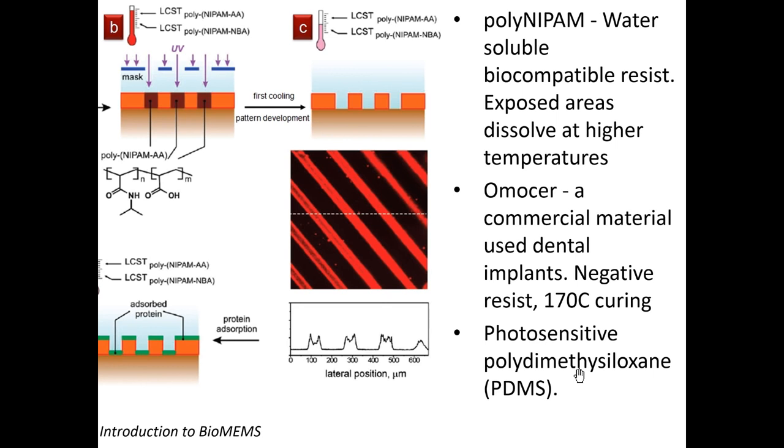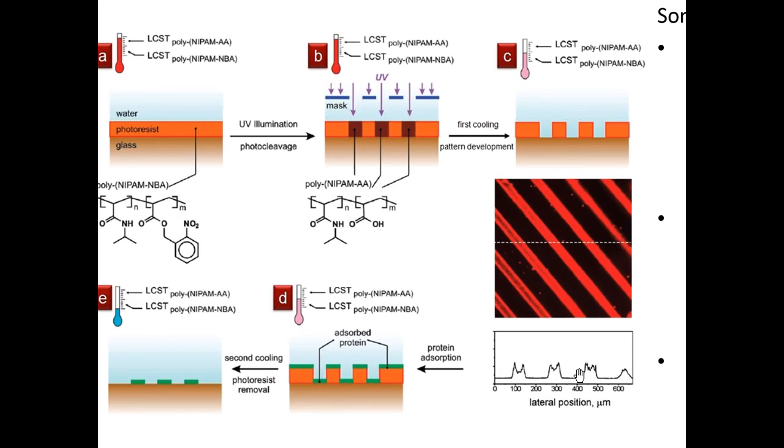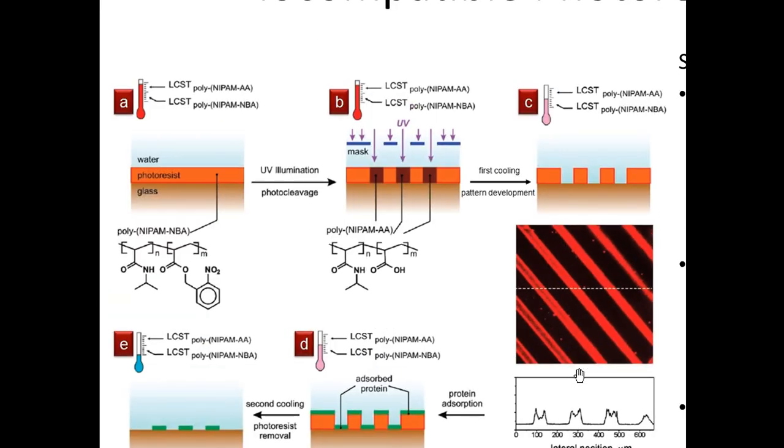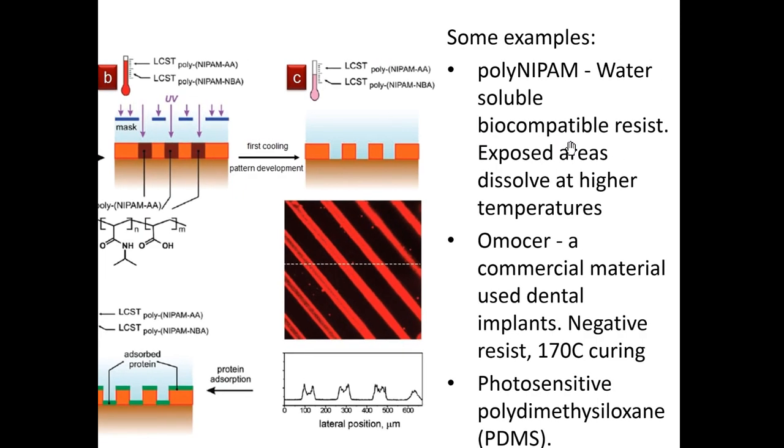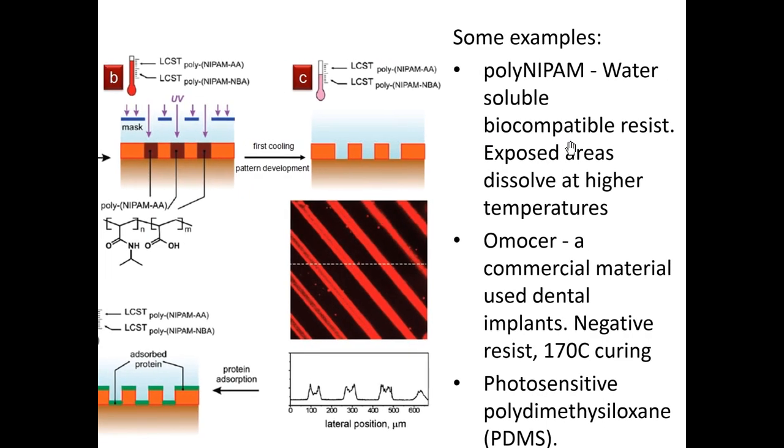So you're not heating this material up. It's just at room temperature, and then you're cooling it. It doesn't show a heating step at all. Oh, so what's happening is that you're exposing the system at a higher temperature, and then you're bringing the system down to cooler temperatures. So you heat it before you actually have to heat it. Yes, that's right. Because interestingly, this material is a thermally sensitive resist, meaning the exposed areas dissolve at higher temperatures.